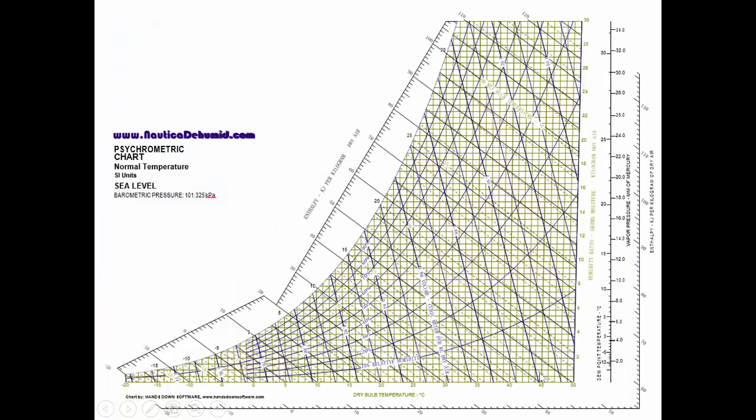If we look at this particular psychrometric chart, as you can see here, the humidity ratio of the air is represented by this vertical axis here, and so if we know the thermodynamic state, we can move horizontally to locate the humidity ratio on this vertical scale in the psychrometric chart.